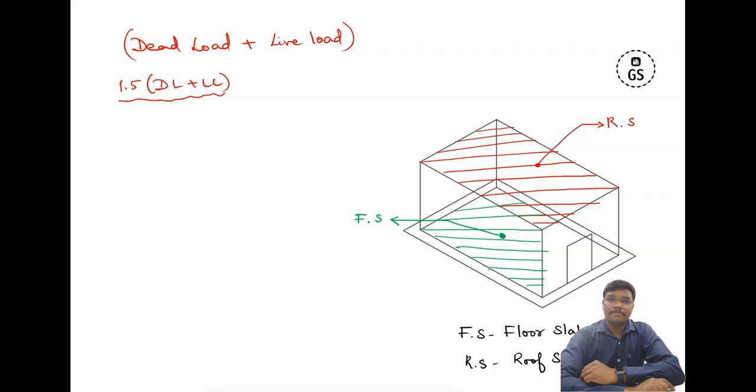At the beginning level, when you are making a model of structures, or we are using STAAD Pro software or any kind of ETABS software, we generally take for static conditions 1.5 times dead load plus live load. When you go further in detail with seismic and wind load analysis, we have various load factors that we will consider and apply to the structure. If you are at the beginner level, starting calculations, you should know the multiplication factor is 1.5 as a factor of safety.